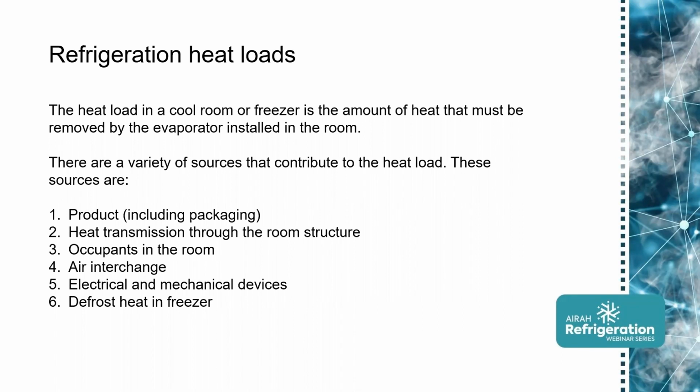And the last one is defrost heat. This is only applicable in freezers, because the evaporators ice up in the freezers, and the ice or frost needs to be removed. Otherwise, it's going to impede the airflow through the evaporator.